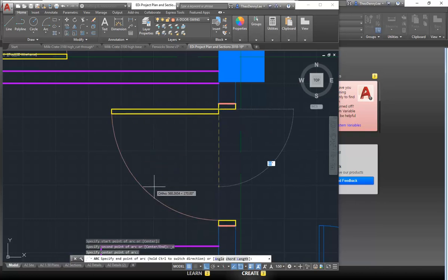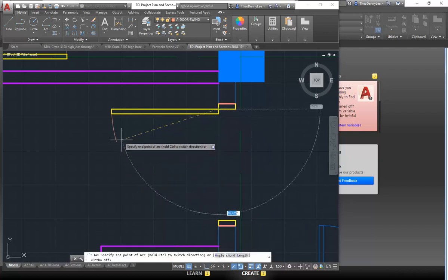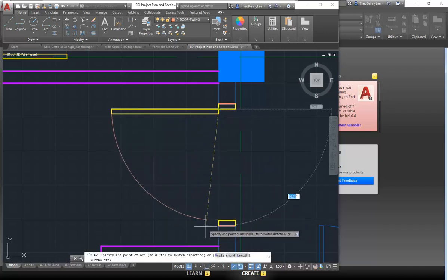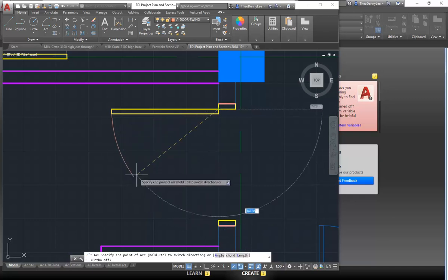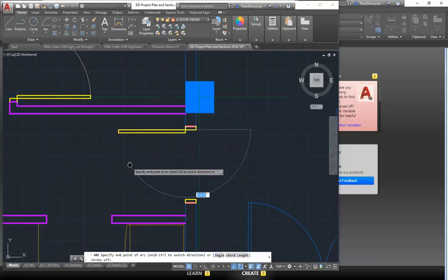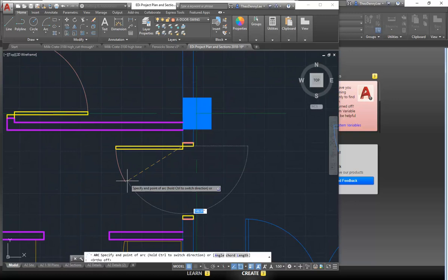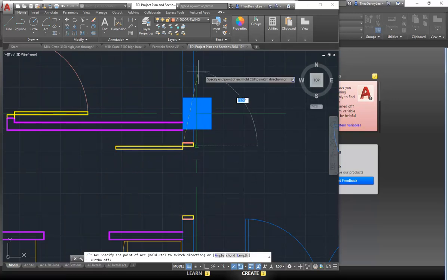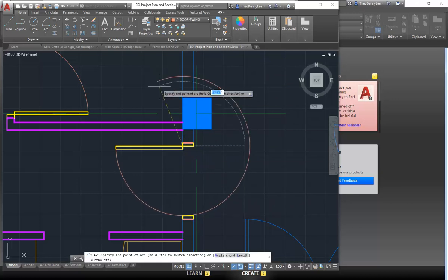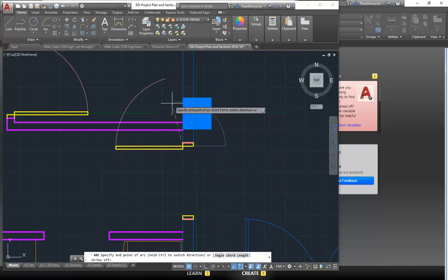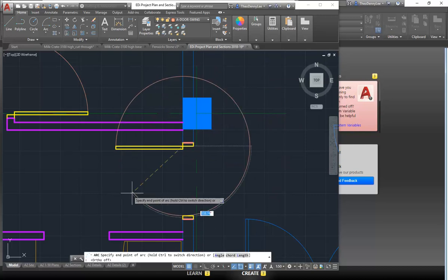And then, because ortho's on, it's trying to just snap to a right angle. But if you turn ortho off, you'll see the swing coming around. And by default, it goes anti-clockwise. But have you ever seen this where you want to make it go the other way? So here it's going around this way. So I'll show you, since you all seem pretty okay with this. Exactly, that's right. And if you forget, they're pretty good now at giving you the prompt down the bottom. So you can always see there, hold control, and that makes it go the opposite way. And that can be helpful.